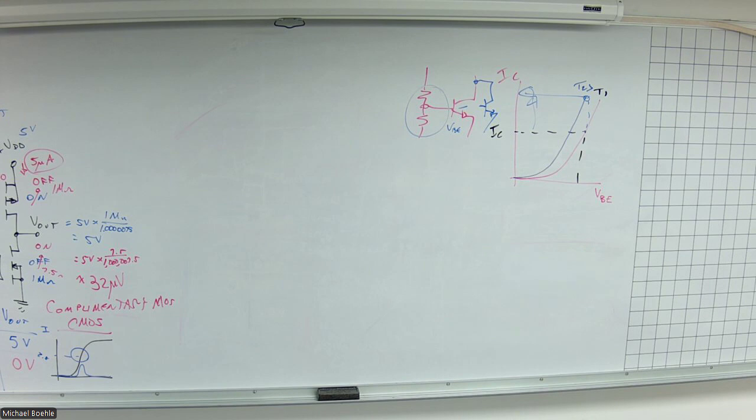Another thing about bipolar transistors, we are using a forward biased base emitter junction, which involves those carriers coming together. Turning that off takes a little bit of time. The field effect transistor can respond more quickly and turn off, because we're just taking away a channel completely. All right.